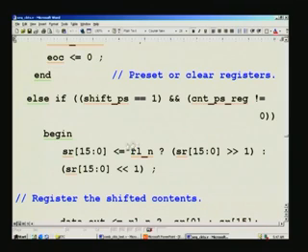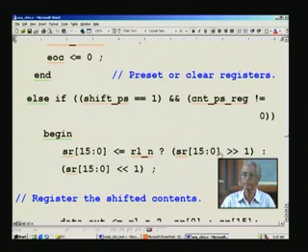Right means 1 here. If this signal is 1, then we do the right shift using the conventional statement, and then assign this back to itself here. So, it is overwriting itself, and then there is one more possibility here. If it is 0, you left shift here. Whether we want a left shift or right shift is merely governed by this. Right shift is done here, left shift is done here, and that shifted result will be transferred once again back to the shift register here.